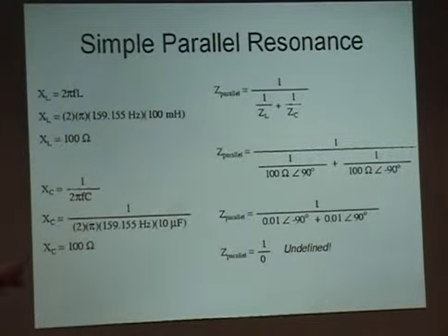Let's go through the next stage where you have series resonance. Think of this as the output of your radio into an antenna. You really want to add a resistor in there too, and that's where your radiation resistor or resistance comes from. You're always going to have some resistance, some inductance, some capacitance in every wire. But this is an antenna system with reactance. What happens when it goes resonant? All of a sudden, all that power shoots up amazingly, and you get great output.